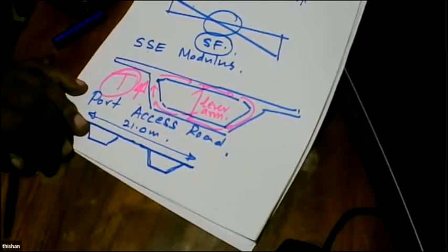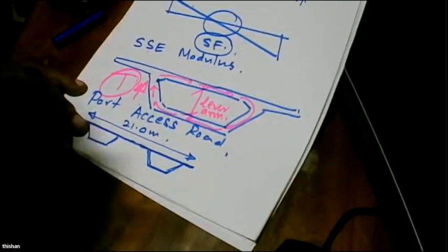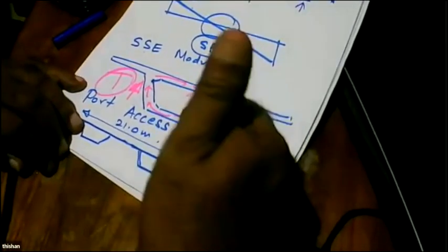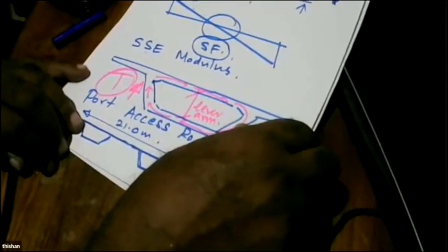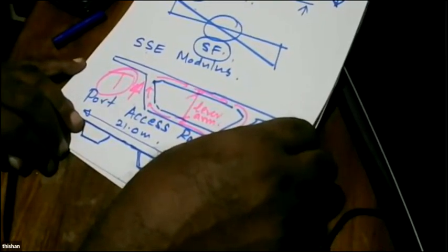Because of that reason, for larger spans like 40 to 50 meter spans, these box girders are preferred over the I girders. Generally, with I girders, we can go up to about 35 meters. Beyond that, it's always good to go for these box girders because they give us a robust solution. Right? So we are going to talk about all these different variations during this lecture series.